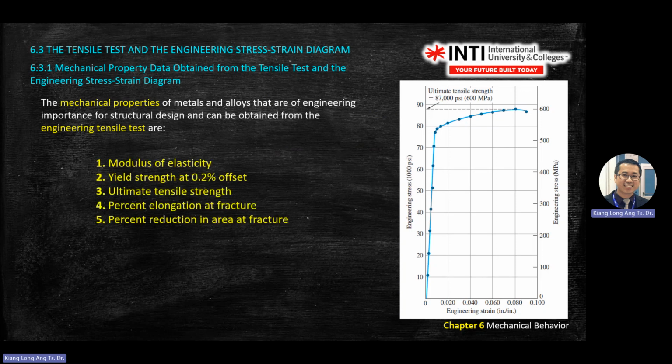So on this graph, we're going to learn all these things. Modulus of elasticity, I already showed you, is y equal to mx plus c, the gradient of the line. And we're going to go into this: how we know the maximum point where it starts to go plastic, or we use the wrong value in our calculation. Here, 2% offset. I just give you the info first before we go into the slides. So I enlarge the graph.